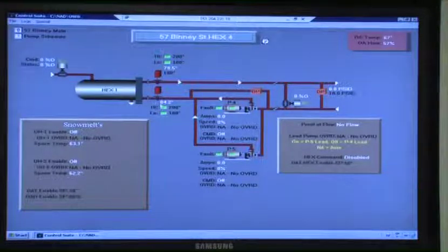We maintain this. We have a temperature set point of 180 we're trying to maintain. We have some high and low alarming. It's off, locked out because of outside air temperature, and pumps aren't running because it's locked out. We've got proof the pumps are running. We have a differential pressure set point and valve down at the second floor, and we have this feeding out to those different areas, and it goes to the snow melts also. The control of when this sends stuff to the snow melts is based on this, and we can override them if we want. And space temp.